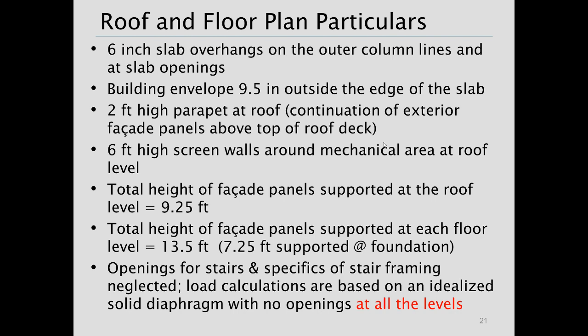And then in terms of working through the calculations, just to keep things simple, we're not going to consider any openings for stairs, etc. We'll base the load combination calculations on an idealized solid diaphragm, with no openings at all the levels.